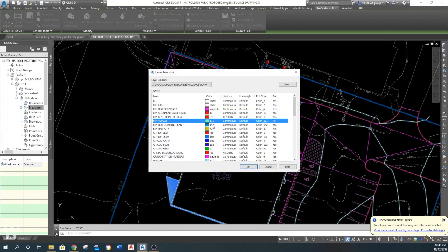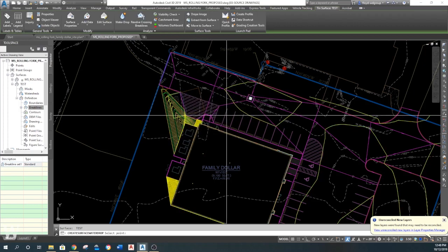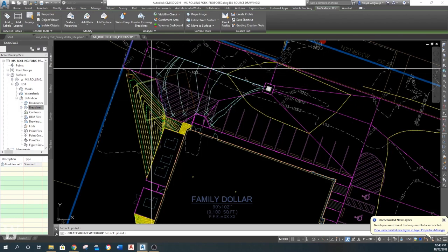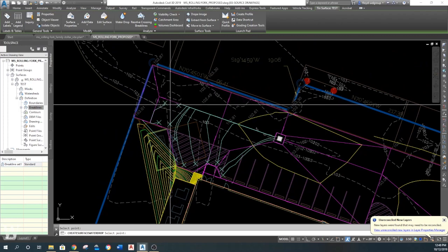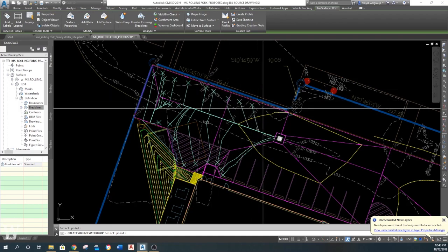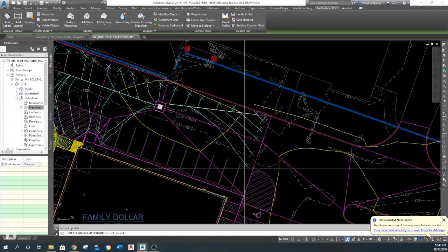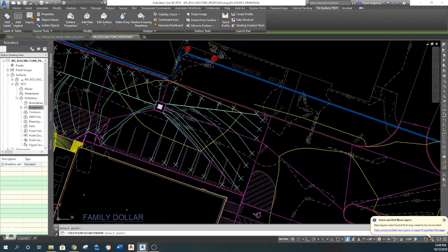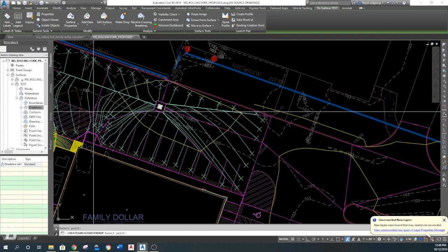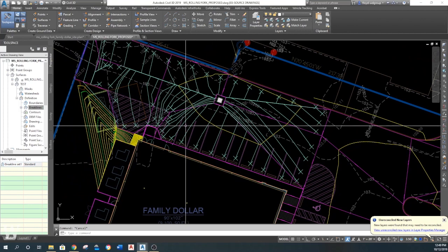I'm just going to click, find a layer that I know I'm not using, so I can erase them, select some and erase all. Then I'm going to come in here and I'm just going to put water drops in. And now, if you notice, they should change right there somewhere, going out to that little flume. But now we got everything running to kind of a center line and down. Alright. I'm not worried about this side because this side was good, if you remember right. So now we know where it's all sloping.